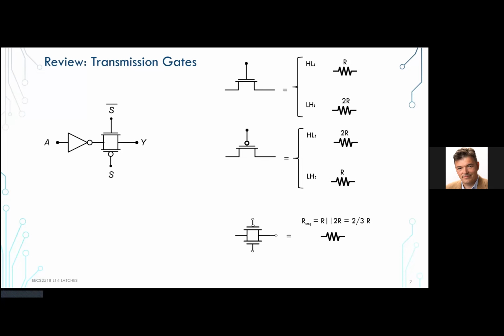What kind of a sizing does that correspond to? 1.5 in a transistor stack. Let me play with sizing over here. Therefore, how should this guy be sized? Also 1.5 in order to get the equivalent resistance of those two to be equal to a single pull-down resistor with a width of 1. The same that we have seen in an NMOS stack.